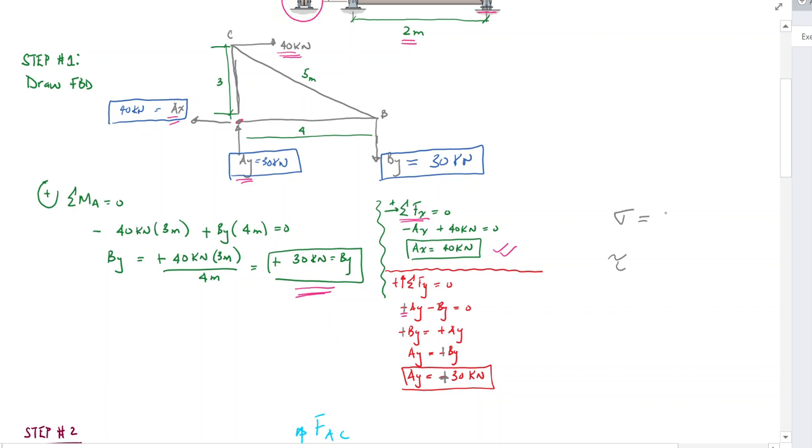Our normal stress is nothing more than the force over the area. Shear stress is also force over area. But what will be the difference in the force for each one? Direction, how it comes in contact with the plane. For normal stress, you have a rectangle and the force is always perpendicular to that face.